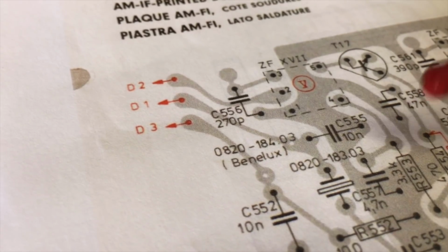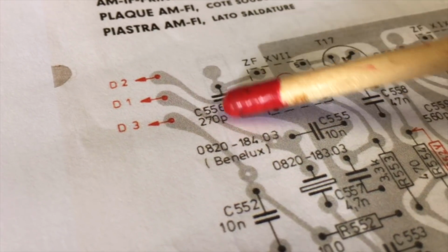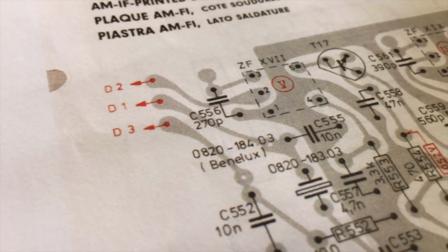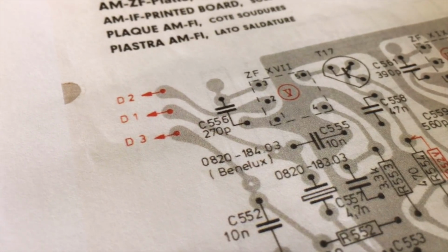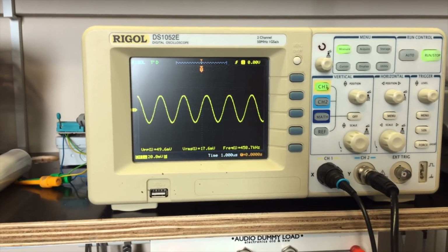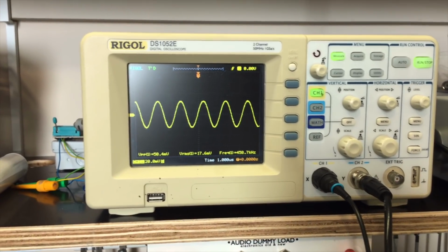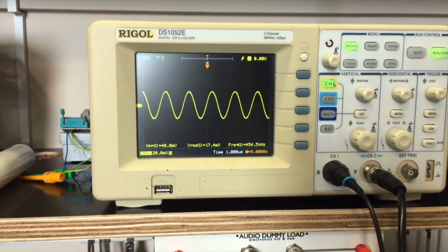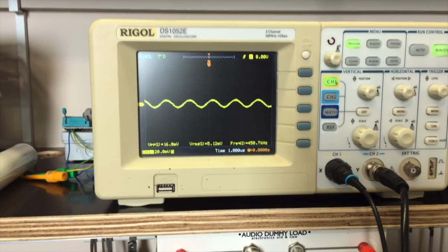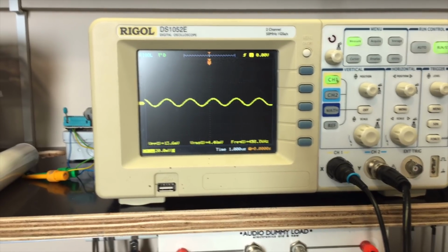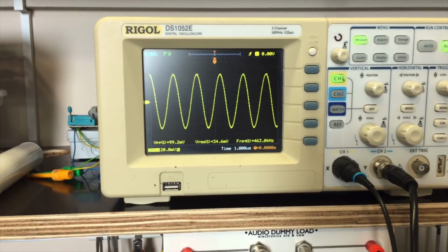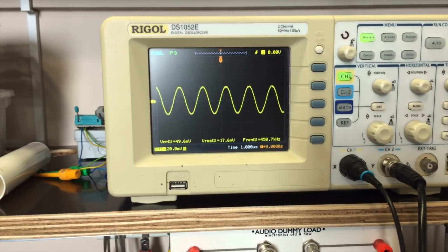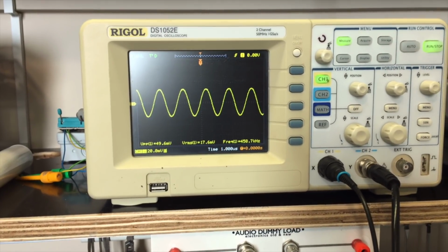So it's going in here, and it's going to go through filter 17, which is the start of that chain of adjustments. And this is what I get on the scope. Now, if I take my adjustable attenuator and I remove 12 dB, or add 12 dB, I beg your pardon, this is in fact the representation of the carrier level, because I've got the carrier going in with no modulation.